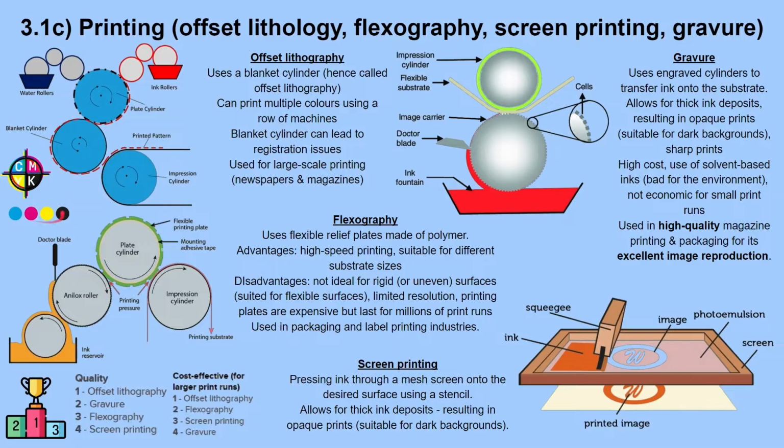You'll also see these color blocks or color circles at the bottom of newspapers, and this is basically to check again for alignment issues, and check that each color is strongly printed, has enough ink in the ink chamber or in the ink rollers. So that's offset lithography, the cost effective and highest quality process, with 3 cylinders, water rollers, ink rollers. So if there's a 4-mark question, explain the process or draw the diagram. This is the diagram you would draw.